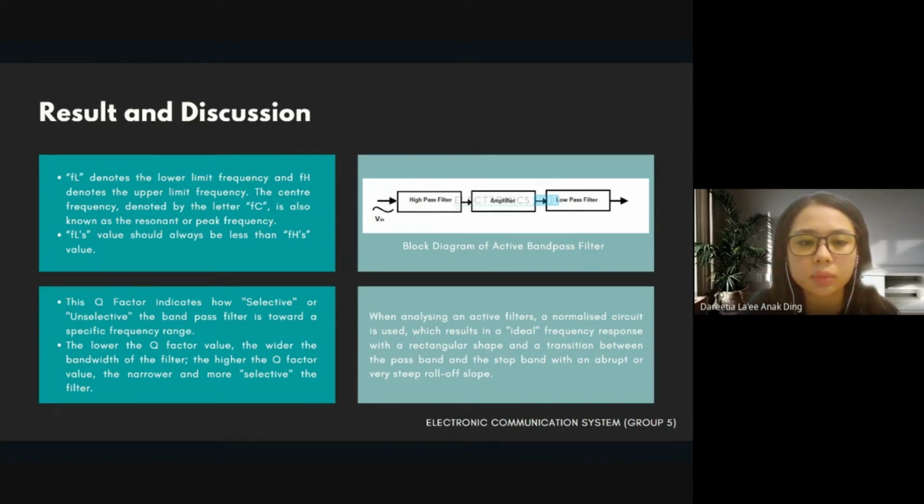The signal will first pass through a high-pass filter, the output of which will tend to infinity, and then to a low-pass filter at the end. The high frequency signal will be filtered out by this low pass filter. The simple band pass filter is obtained by cascading the high pass filter and the low pass filter. The low pass and high pass circuit must be connected in the same order to realize this filter.